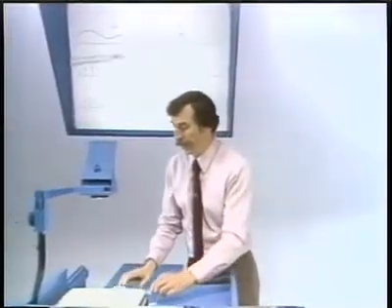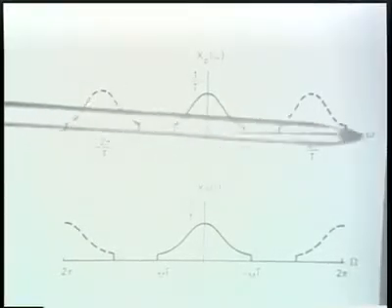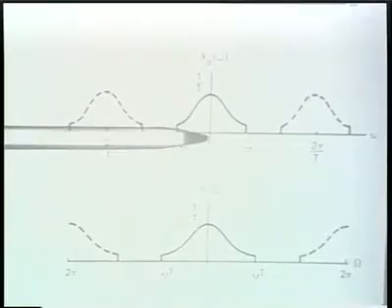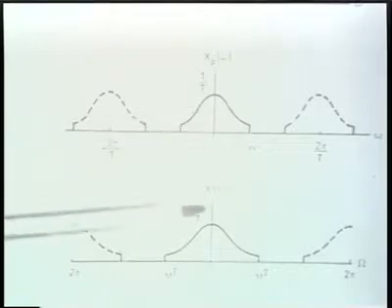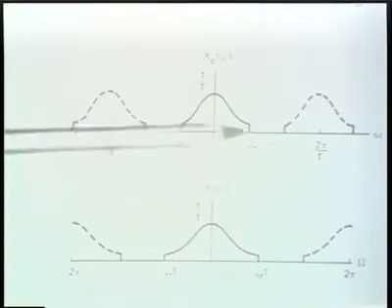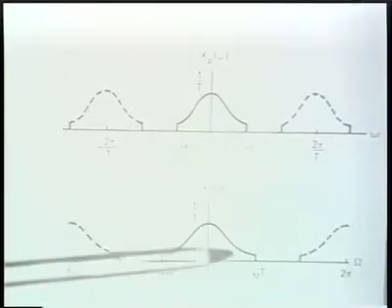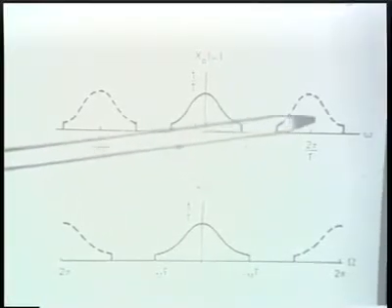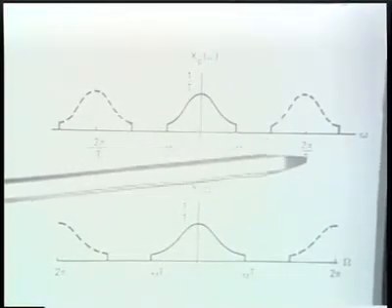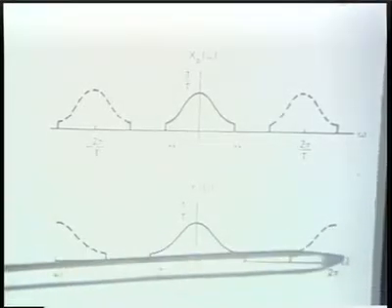Well, dividing out in the time domain by capital T would correspond to multiplying the frequency axis by capital T. And indeed, what happens is that in going from the impulse train to the sequence values, we now rescale this axis so that, in fact, the axis gets stretched by capital T, and the frequency which corresponded to 2 pi over capital T now gets renormalized to 2 pi.